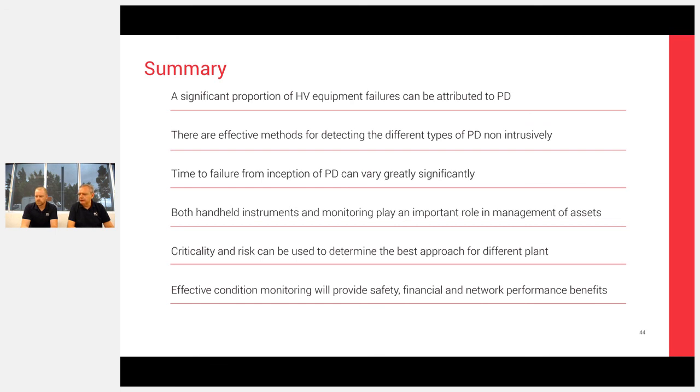We haven't actually had a failure on our Australia, New Zealand monitors, touching wood. We've prevented quite a few. We haven't actually had a failure occurring on our watch. It could happen. We're not claiming otherwise. If anyone does claim that partial discharge will find every single fault, then they're telling lies. There will be elements of failure out there which we won't see before it fails. Often the quick ones.